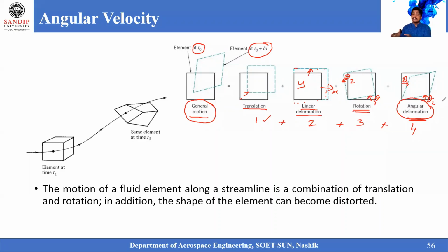This may be possible with all four types, right? So how do we predict this? We place a streamline along this particular fluid flow, and based upon that streamline behavior, the streamline definition is dx by dt. At any point along the fluid flow, if you are tracing that velocity, that velocity is exactly the tangent to the curvature of the fluid flow.